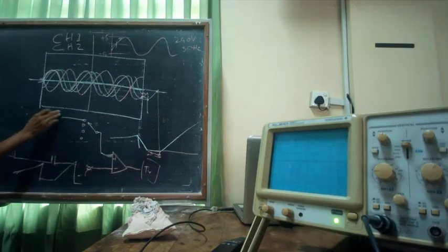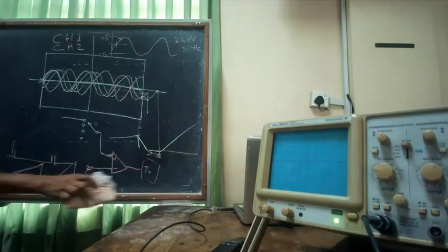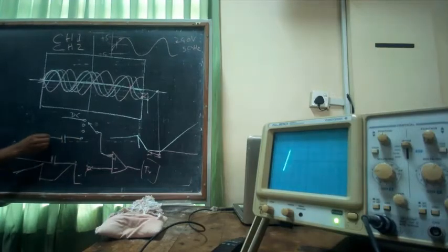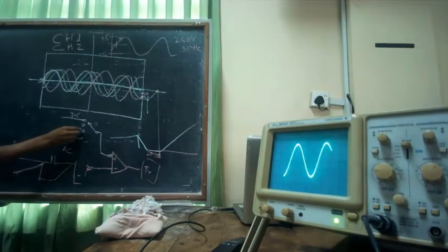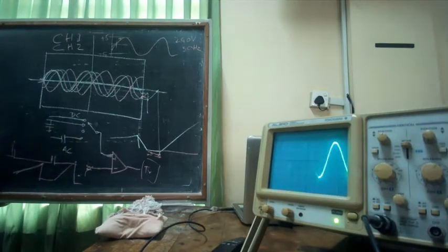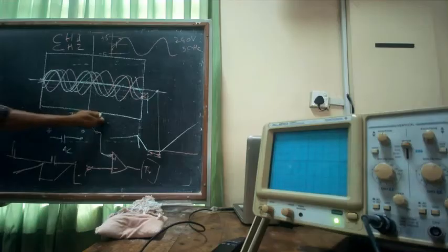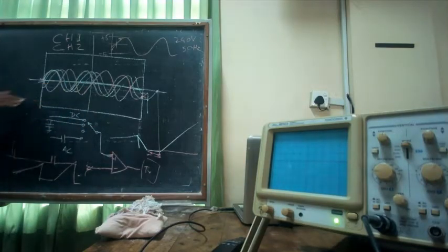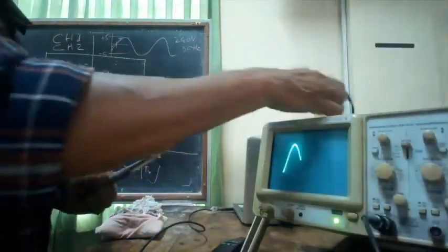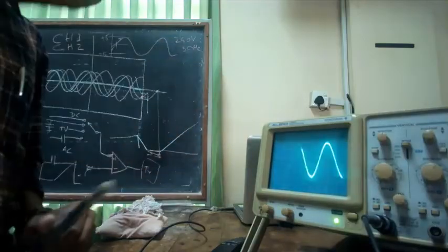The first one is DC, this is AC, and high frequency reject is something like this, so that high frequencies will go through this capacitor and short circuit into ground. The high frequency noise will not get to the comparator. The last one is TV. For TV signals, there are vertical and horizontal signal specifications. If you are using an oscilloscope to diagnose those, you can use that setting. We are not going to talk about that.